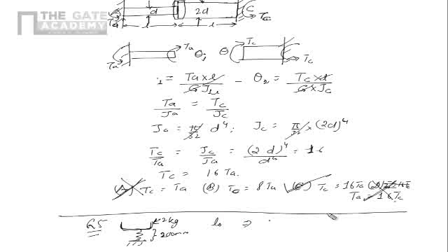So that gives us a relationship saying that 2 multiplied by g, which is the acceleration due to gravity, is k into L0 minus 0.2. 200 millimeter is nothing but 0.2 meter. And assuming that k is the stiffness of the spring, that gives us one relationship, which is 2g equal to k into L0 minus 0.2, where k is the spring stiffness and L0 is the undeformed length or the original length.